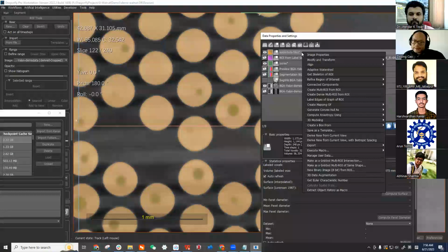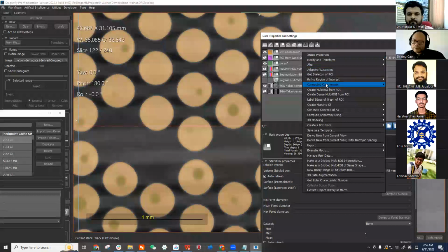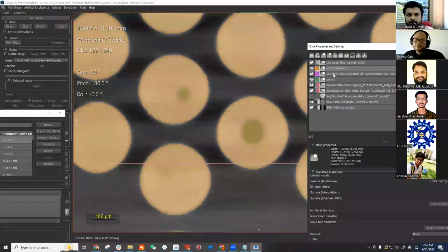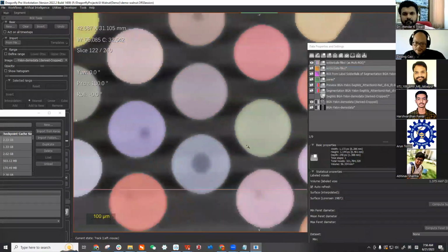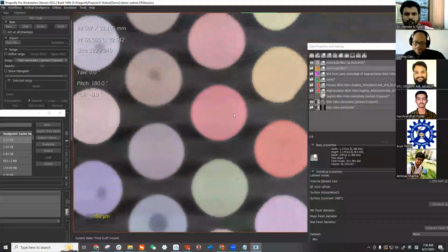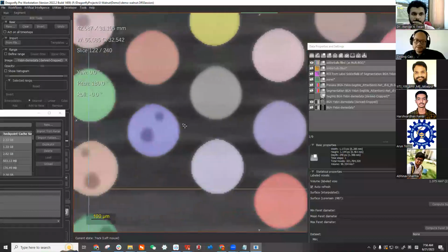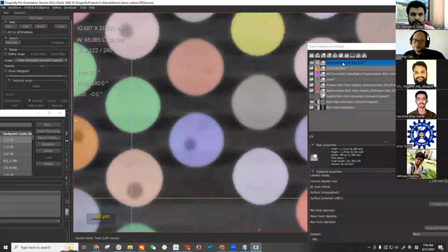Then we can generate the multi-ROI from the ROI. This is the ROI. From the ROI, it means it labels all the solder balls as one class. And by doing the multi-ROI, you see each ball has been labeled differently. So this is instance segmentation. We could label each instance differently because they are disconnected from each other. So we can do this very quickly.